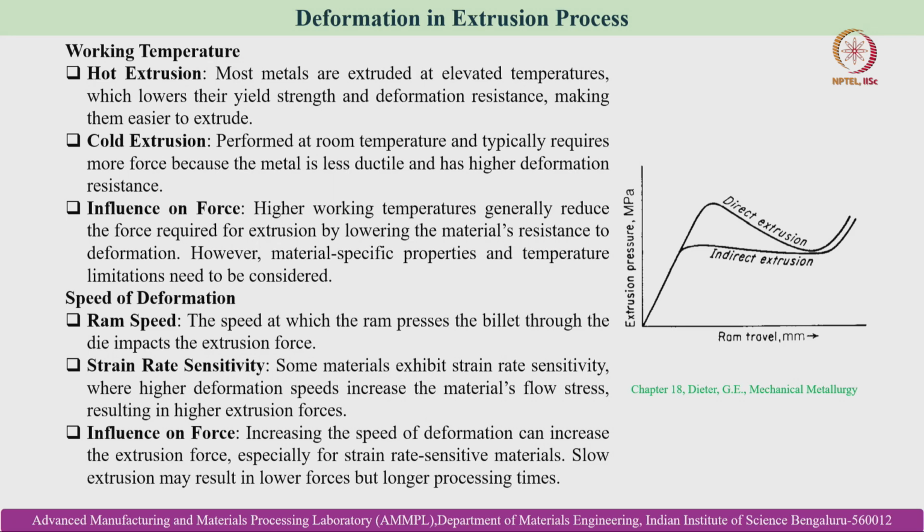So, the influence on force: higher working temperatures generally reduce the force required for extrusion by lowering the material's resistance to deformation. However, material-specific properties and temperature limitations need to be considered before analyzing the influence on force.